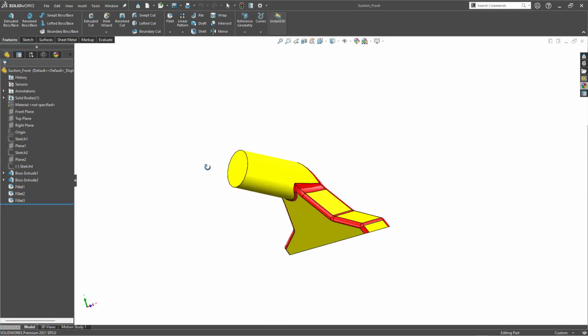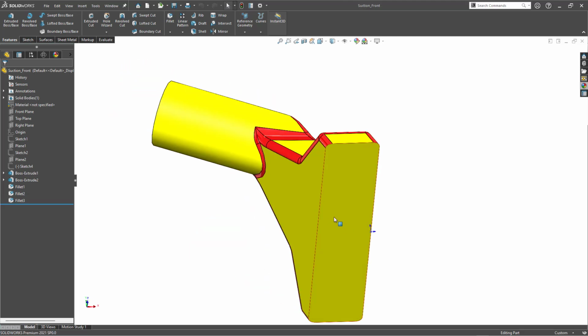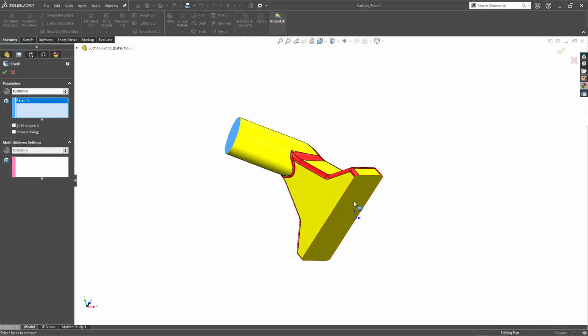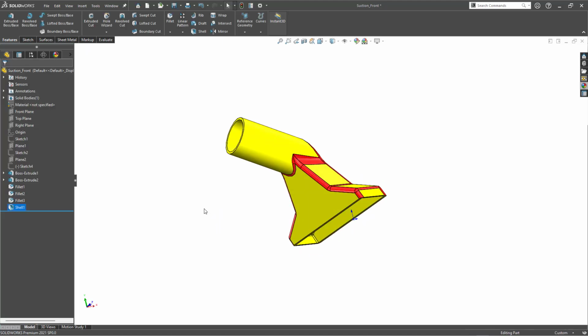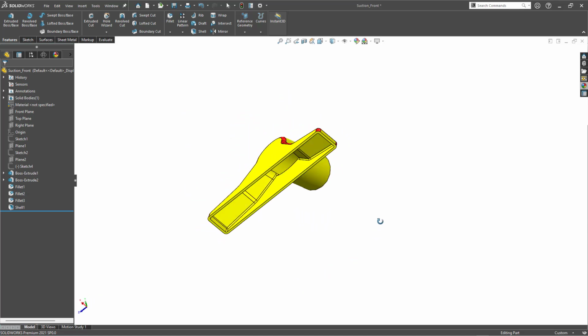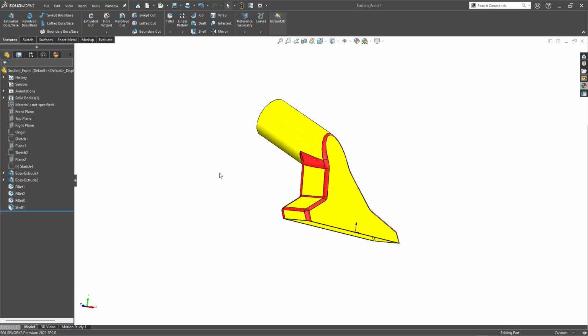I would like to have the uniform thickness of 2 mm everywhere, and I would like to have the cap on both the sides. In this case, what we should do is you can use the shell feature. These two faces which I'm going to remove, faces to remove. Yeah, the shell thickness of 2 mm I would like to have it. Yeah, if you specify these two, more than sufficient. Software will take care of everything. The fillets, you can see outside fillets will match to the inside one, and this is how it will be generated.